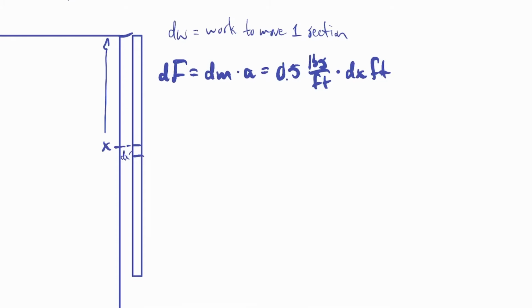When we do an example with SI units, this might be a little more straightforward, but we have to do some in non-SI units. So now I have to multiply by the acceleration due to gravity, so times 32.174. I'm going to round to 3 places. We don't need to keep 6 places all the time. And this is feet per second squared.